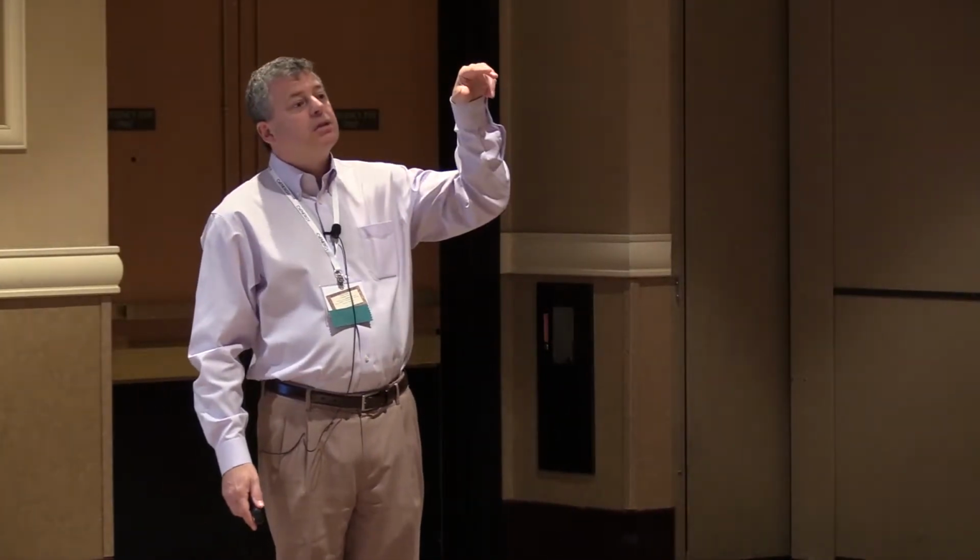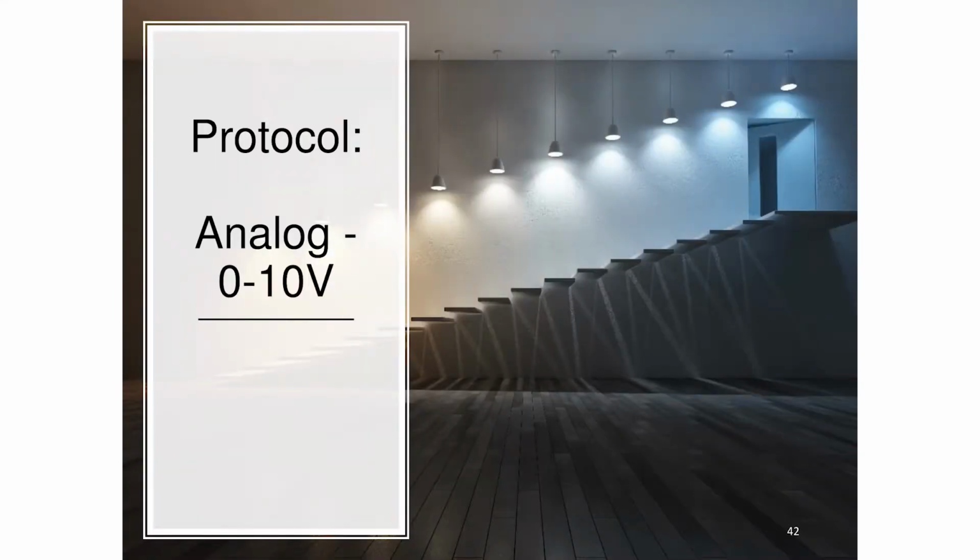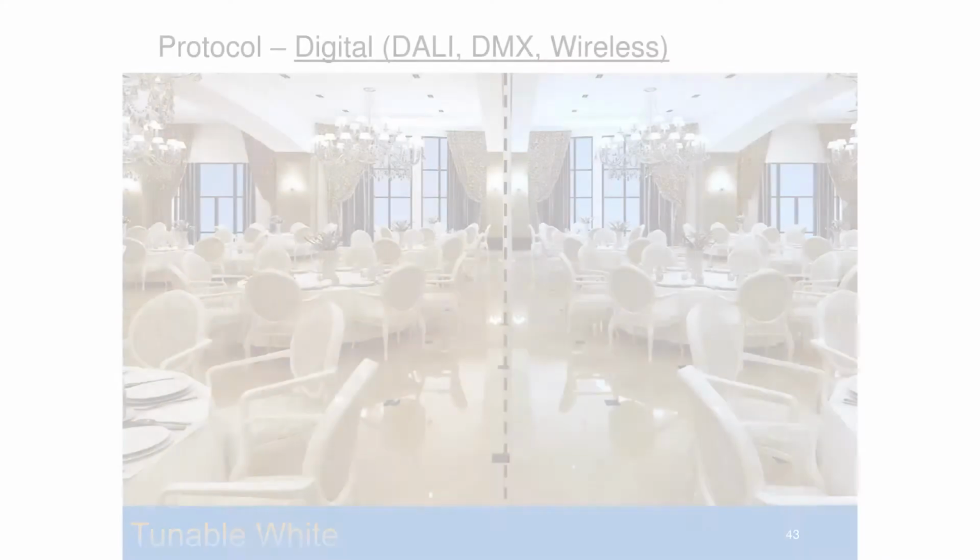The challenge you get into is that as you get into different inputs in that fixture, the 0 to 10 volt, which has basically a voltage and a common, 2 extra wires, I now have to potentially send 2 of them to every fixture. So I now have 4 wires on top of hot and neutral. Again, it may not be something that I'm showing you on the screen, but it's basically going to increase your number of wires because I'm increasing what I have to put to each fixture.